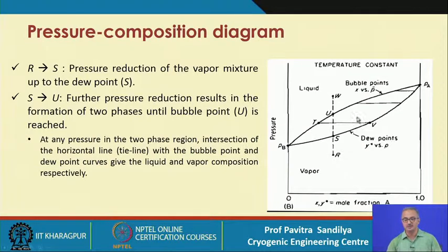Okay. So, in this we find that here we are getting the compressed liquid and that is represented by say point W here, and a similar thing will happen if we start from point W, that is liquid state, and keep lowering the pressure. First we will approach the bubble point pressure, and with still further lowering we shall go to the dew point pressure, and ultimately we shall go into the superheated vapor region.